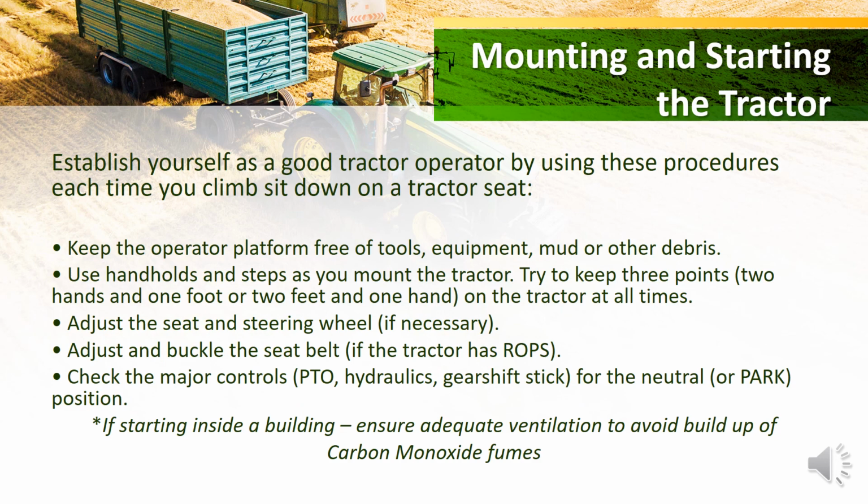Now, you should establish yourself as a good tractor operator by using the following procedures each time you climb into a tractor and sit in the seat. Keep the operator platform free of tools, equipment, mud, and other debris. Don't be throwing empty cans of soda and bottles around that can cause accidents. Use the handholds and steps as you mount the tractor. Try to keep 3 points on the tractor at all times. So 2 hands and 1 foot, 2 feet and 1 hand, but there should always be 3 points of contact as you mount the steps.